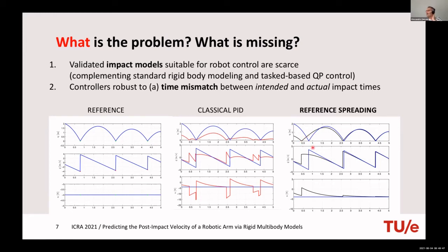And so this black line is the trajectory that one would expect when having such a reference. The message here is essentially that by using the same controller, the same PDs, the same gains that you see in the middle plots, you get way better performance just by changing the concept of error that you use for tracking. So by changing the definition of error, you get better performance.